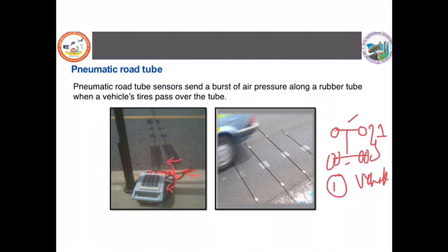The second disadvantage is that air pulses, or pressure, will be created, and with that pressure the automated counters are activated. But for some vehicles, the pressure developed will not be sufficient to send the impulses to the automatic record counter.